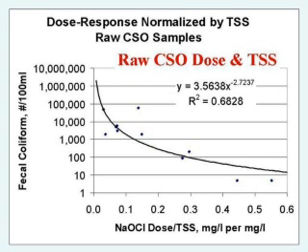Bromine, there's a new product. Bromine has BCDMH, just like the stuff you put in your jacuzzi to disinfect the water. It actually comes in powder form, or can come in a thixotropic solution, and it disperses very well into the effluent. Instead of chlorine forming chloramines, the bromine forms bromamines, but dibromamine is the main component when it forms with ammonia, and it's very unstable. It's much more reactive than the chloramines, so it's a very fast oxidant that dissipates quite fast, though. So these are some of the other disinfection options besides, say, UV disinfection and possibly ozone.